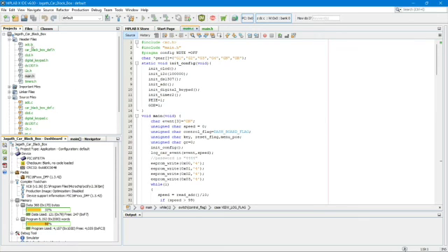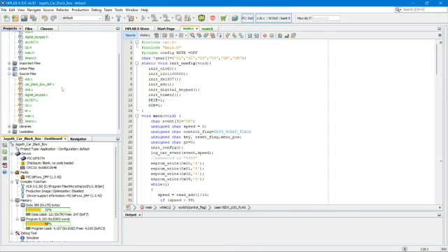These are the header files. The first is ADC, and this is the car black box definitions, CLCD, digital keypad, DS1307, which is an RTC chip, and I2C, and main header files and timer header file. And I also created the source files separately. Same as the header files, I created separate source files for my project. Come on, let's get into this simulation.